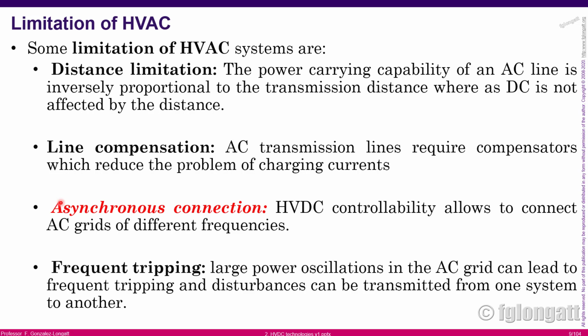The only solution is using HVDC, decoupling the frequency, and that was the reason that Itaipu in Brazil has this back-to-back converter and HVDC transmission system, in order to interconnect two systems with different frequency, okay? Okay, I was talking about the frequency that we want to know.